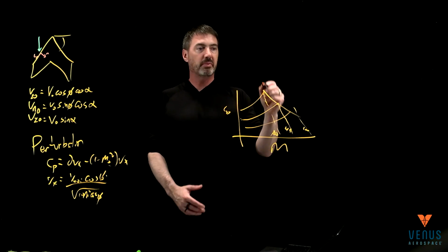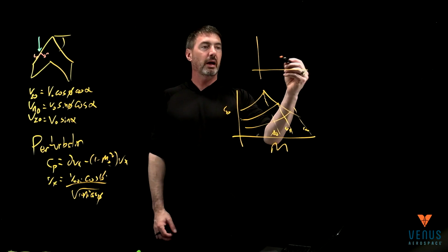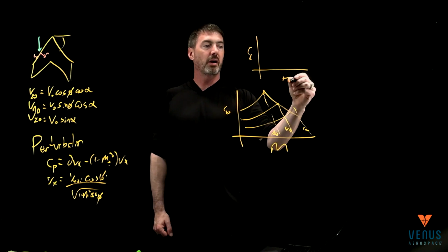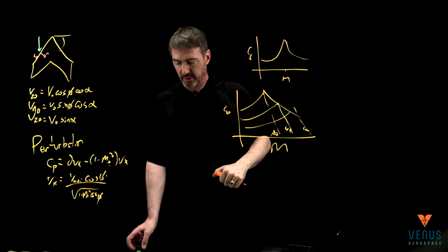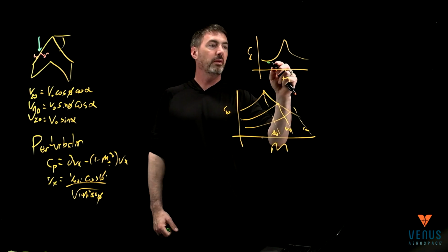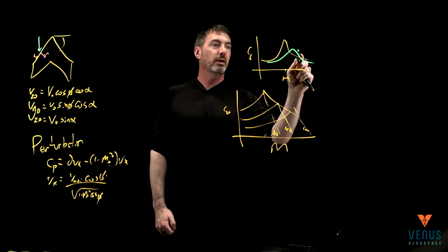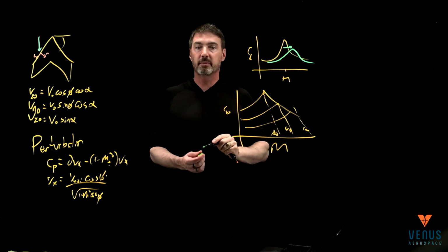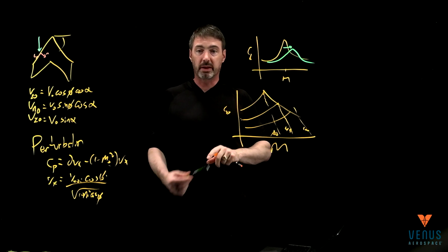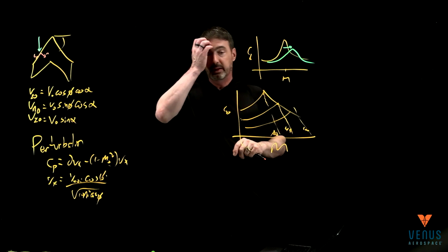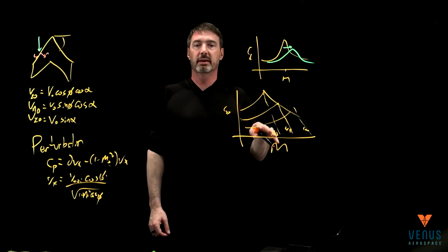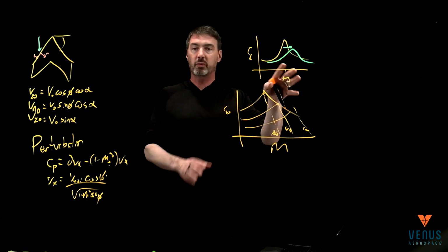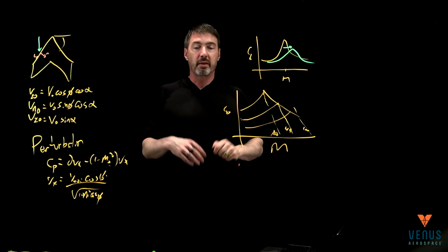And in past episodes, I've talked about how if you're drawing drag at a Mach number of 1.0, there's sort of a drag wall, and that any sweep is doing two things. Sweep is reducing the size of that wall and shifting it to the right. So we've already talked about it. I'm jumping way past the math on it because the effect is important, and it's one that's already understood.